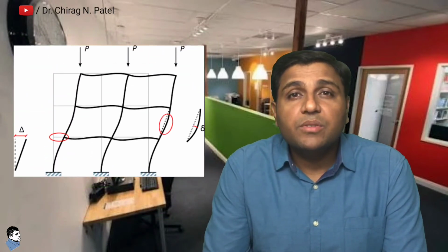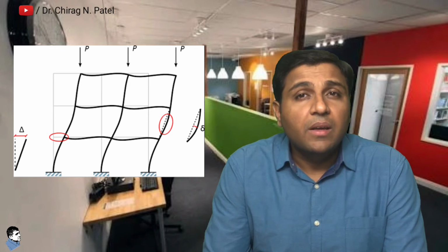Now, if we talk about P-delta effects and separations between structures to prevent pounding, these must also be checked. Specific elements such as external cladding and columns sized for vertical loads but not seismically detailed must also be checked to confirm that they can withstand the deflections imposed on them during the design earthquake or not. The greater the drift, the greater the likelihood of damage.